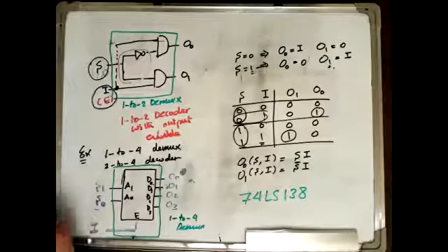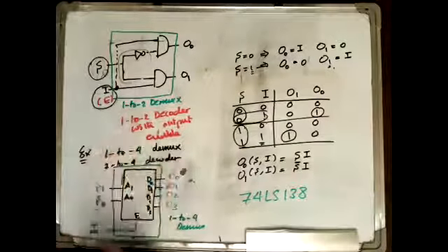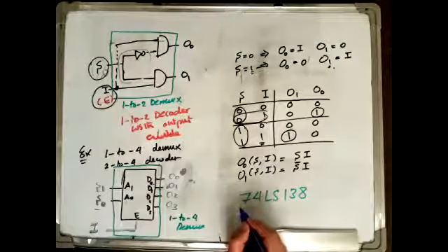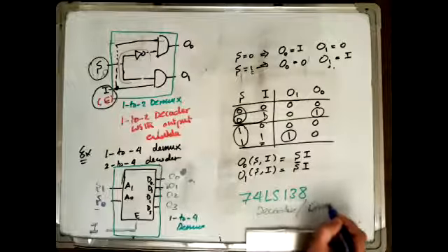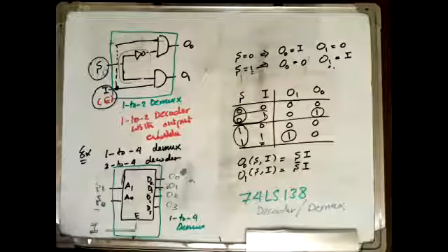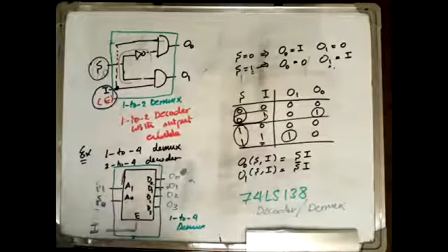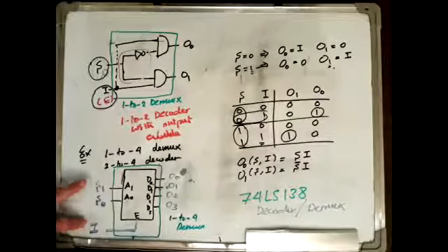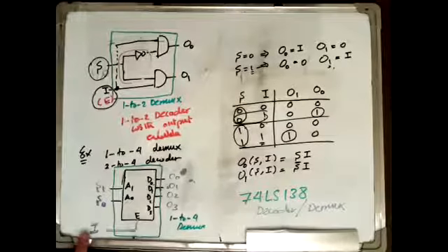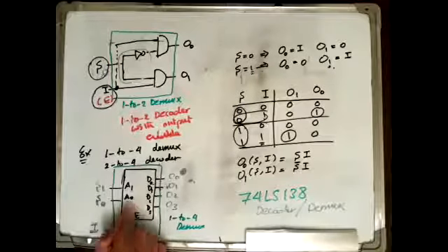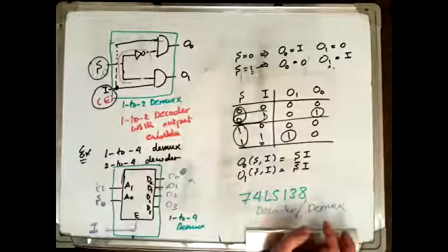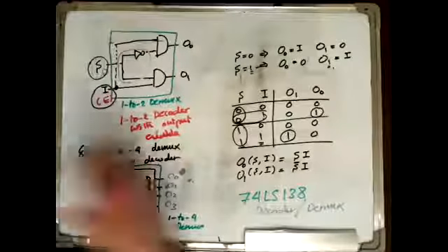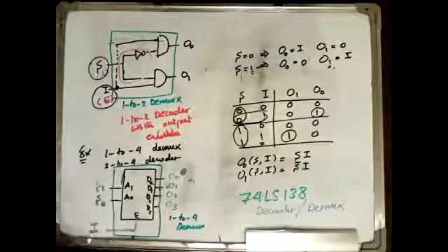So if you go today and search for an IC, with number 74LS138 or any IC that contains a line decoder, you will find in the file that describes this integrated circuit, the title or the name of the circuit inside this chip, for example, it always writes decoder/Dmux. Any circuit that implements a decoder with output enable can be used as a demultiplexer by simply wiring it up the way we talked about. The enable is connected to the data of the Dmux, and the selection lines of the Dmux are connected to the address lines of the decoder. An IC that implements a decoder is basically an IC that can be used as a demultiplexer. So we don't need to do all this if we want to design bigger demultiplexers.